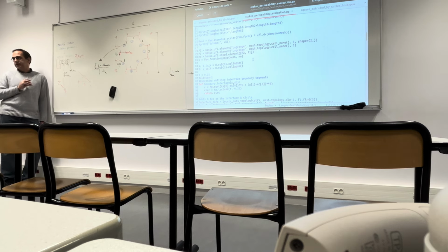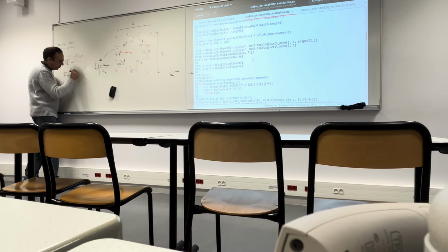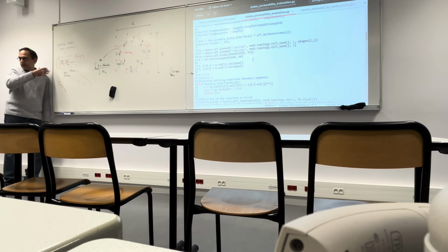This is the simplest choice that we can imagine, considering linear elements. So you have a function which is 1 in i and 0 in j, and the other one which is 1 in j and 0 in i. You can complexify things introducing nonlinear shape functions, but this is the main idea.